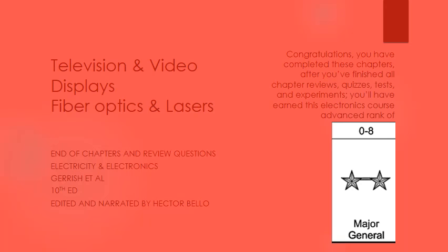Accelerating the electrons in this manner caused image distortion and decreased the tube life. First generation devices combined the 3 stages of night vision viewing into a single structure, the intensifier tube. Improved materials were used to convert light to electrons, and the units operated at lower light levels. However, these devices still had the same drawbacks of distortion and decreased tube life as the original.